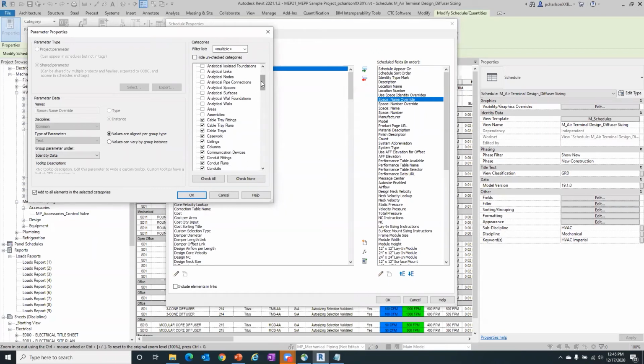And that kind of goes back to what I was saying in the PowerPoint with the shared parameters, in that it doesn't have to necessarily be one item, one category that it's assigned to, like an air terminal. It can be assigned to a number of different categories over different disciplines. So in this case, we got the HVAC, we've got our electrical showing within here. We got architectural, we got curtain wall type information, we got doors, devices within here, furniture, generic models. So all those items are basically attached to that item within there.